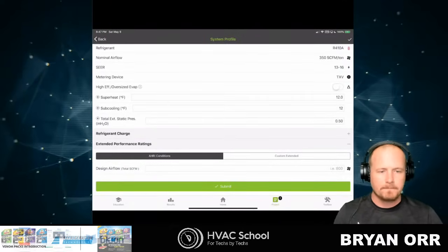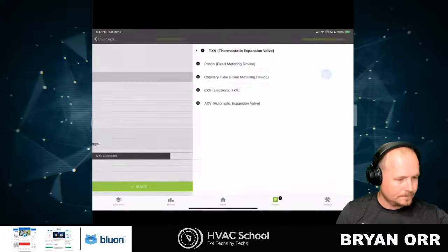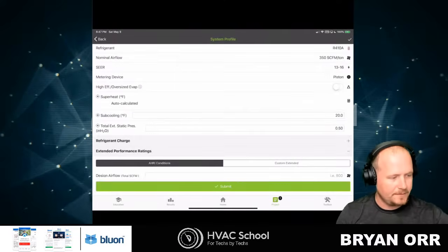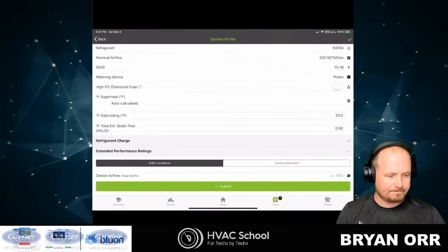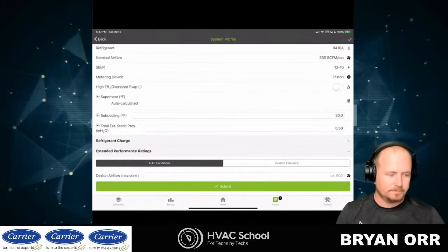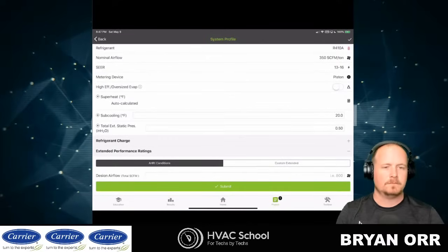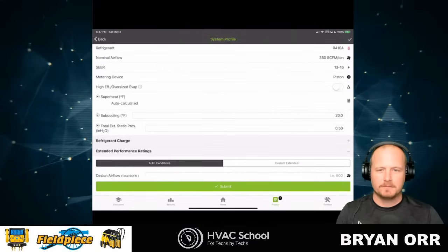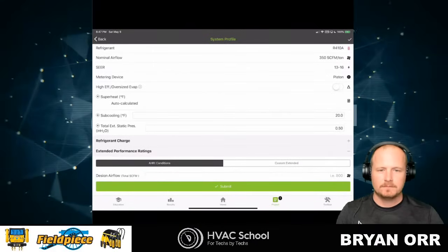Right. So why don't you change the metering device real quick, Brian? Just change it from fixed to TXV or TXV to fixed. Okay. So we're going to go to a piston. All right. And then you'll see the superheat's calculated. So we do a lot of this stuff automatically for you, so you don't have to worry about it. Why did our subcooling target go to 20 when I went to piston? Because you got to have some subcooling.